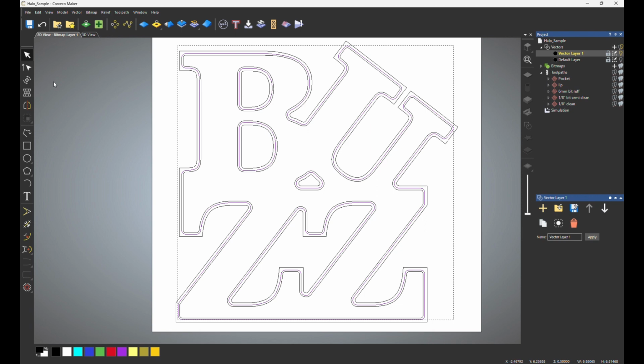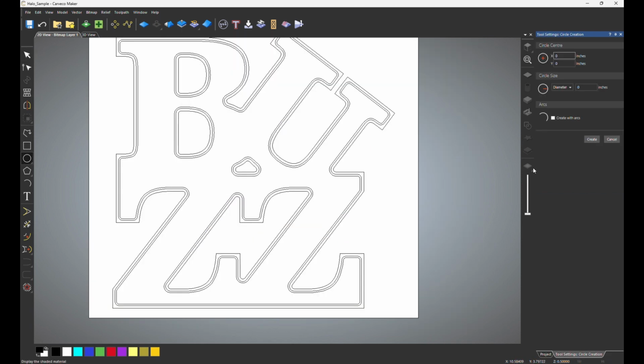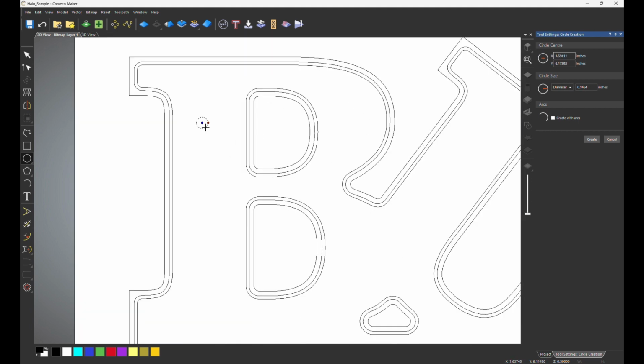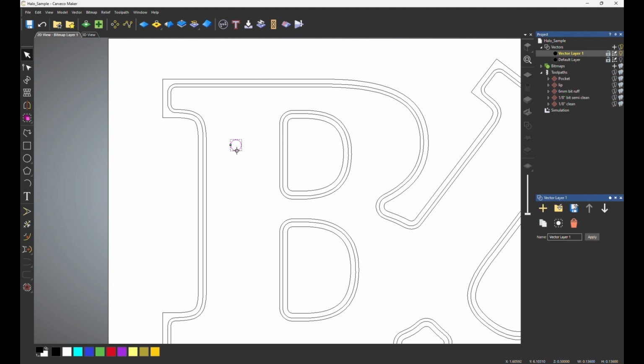One more thing we should do, which would normally be done in your CAD software if you had a whole sign with a bunch of letters, is you would have your pinpoints, so that way you could print or plot out your pattern with all the pinpoints on your paper. I use a 0.136 size hole, 0.136 of an inch diameter. That is a size for threading a number 8-32 bit.